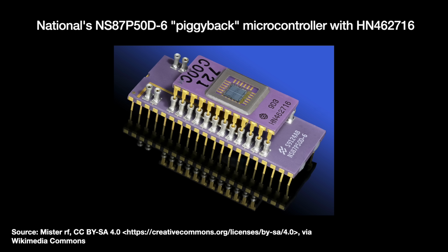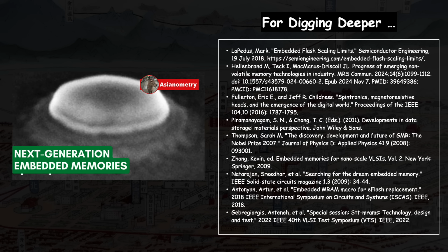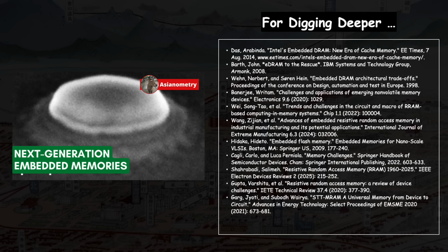The current major hope for these embedded non-volatile memories technologies is AI. Since embedded memories are so close to the logic, literally, there is some potential to evade the von Neumann bottleneck, and that seems to be the case with STT-MRAM. Another option is for doing AI inference on the device at low power and fast latency, maybe even using neuromorphic principles to do so. This is more for ReRAM. In both cases, the technology seemed to have gotten ahead of the use case, though we shall see if the end user markets can get on board.